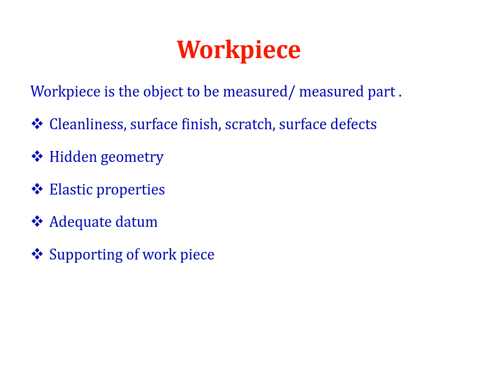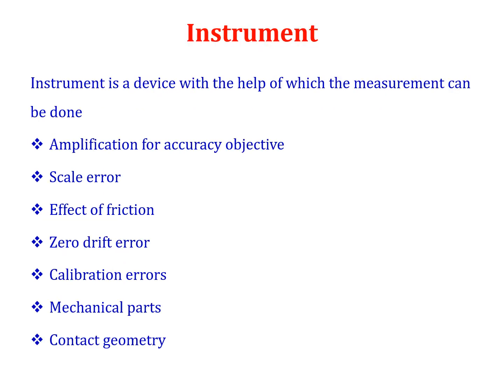The workpiece should be clean, tidy, and should not have any unwanted materials or scratches. It should be of good finish. That is the basic requirement before doing the measurement. Elastic property will also influence the measurement. Supporting the workpiece will also influence the measurement.